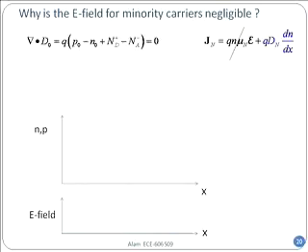So, in the last two slides, you have seen that I have neglected the electric field, and dropped out the drift term, and I have only retained the diffusion term. Now, this is only appropriate for minority carriers. For the majority carriers, I cannot really get rid of the drift term, and therefore the electric field in that case, I cannot assume it to be zero.